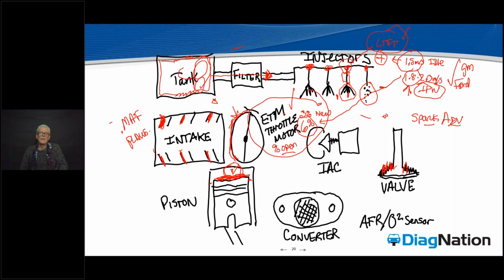As that carbon builds up, what are we essentially doing in here? We're reducing the amount of space, or we're negatively affecting the volumetric efficiency of the engine. Remember, this goes back to a fuel map. X equals 3.5 liters. Now, as this slowly builds up, we no longer have 3.5 liters. What's going to happen as that air gets interrupted and all these deposits are building up exactly as we've shown you today is that the NOx sensor is going to have to step in here and correct for some of that volumetric efficiency issue.